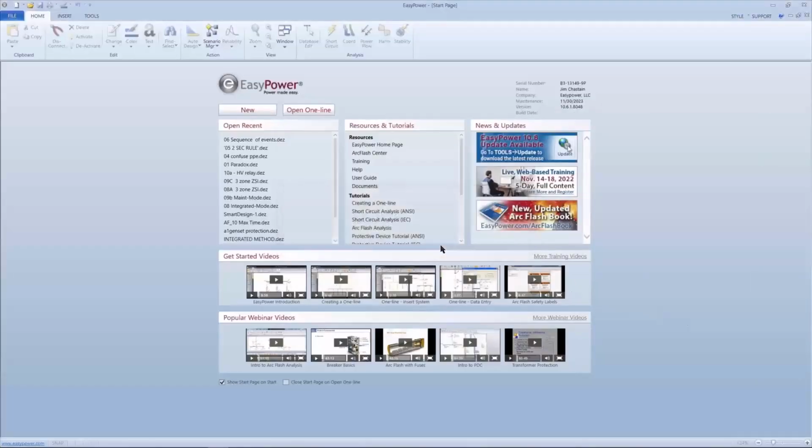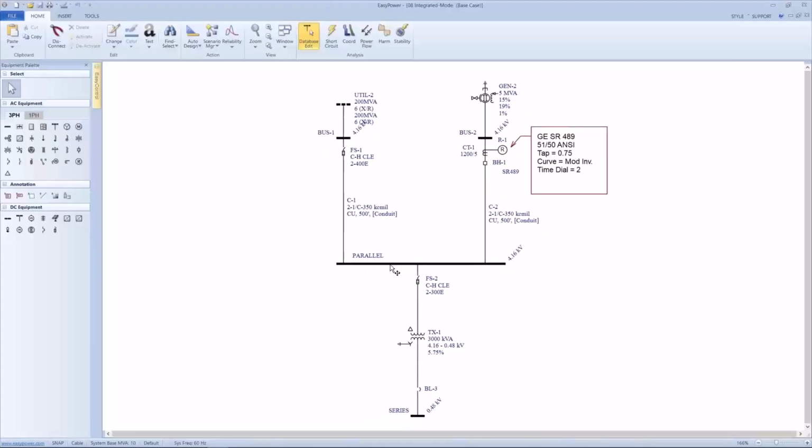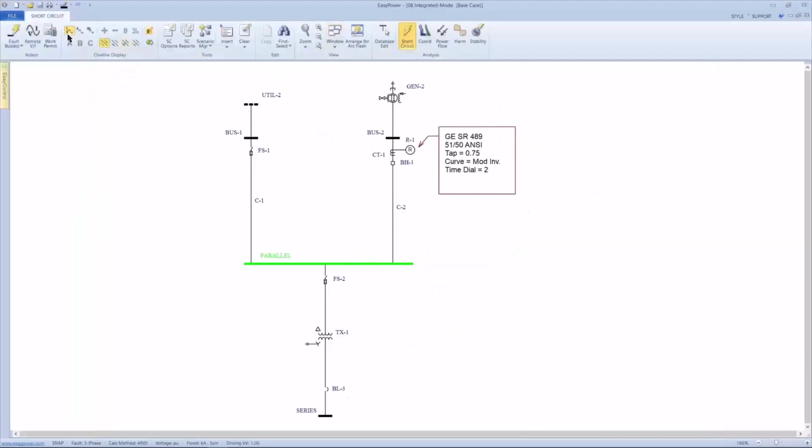Now again, the purpose is to identify multiple sources that may have different fault currents and different trip times, and make sure that the integration for a downstream protective device is being done with the proper amount of current, with a more reasonable assessment of what the actual current is. So if we look at this particular bus and look at the arcing current or the fault current,